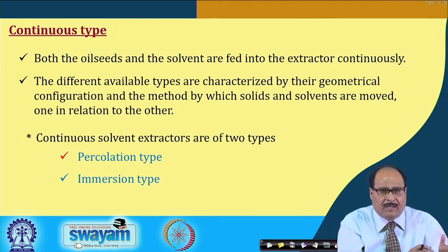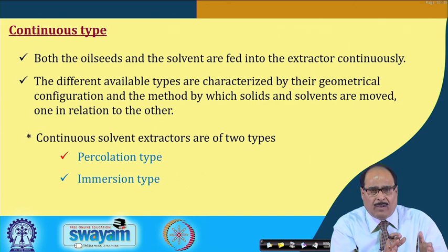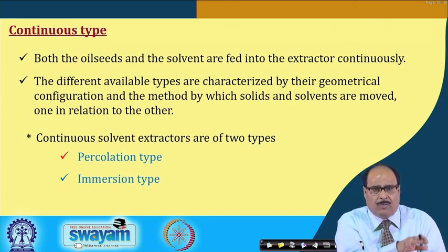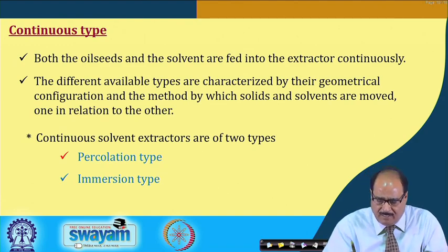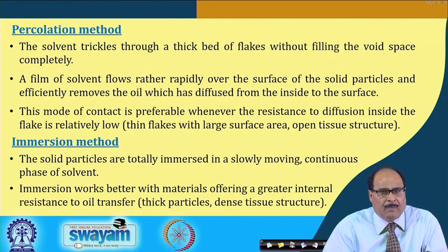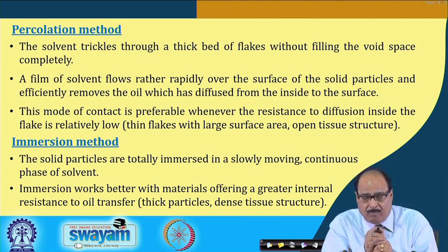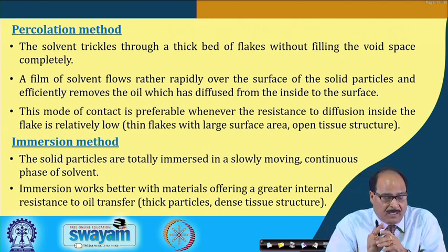However, modern extractors are also available which are of the combination type, that is, both percolation as well as immersion setup or assembly is provided in the same extractor. In the percolation method, the solvent trickles through a thick bed of flakes without filling the void space completely.